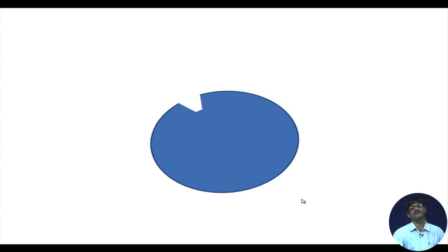So, you will find a lot of effort will be spent for correct angular movement of the gear blank due to indexing. Why? Because on this depends the accuracy, geometric accuracy of the gear. If we make a mistake, or if there is inherently some mistake in this rotational process, or if we suffer from say parallax or due to a large least count, all these things will be leading to errors in the gear teeth, and once you have errors in the gear teeth, they will not function properly.